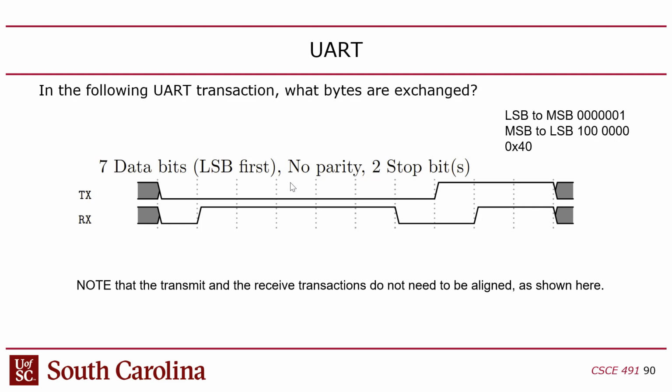Now, by the way, if you're getting consecutive bytes on UART, it means that someone's dumping text to you, right? But if you're typing, you're not sending consecutive bytes because there's going to be dead time between your keystrokes. But if you are sending consecutive bytes, like printing out a directory listing over a UART channel, having more stop bits will separate the bytes being sent a little bit more. And this is presumably for signal integrity purposes, right?